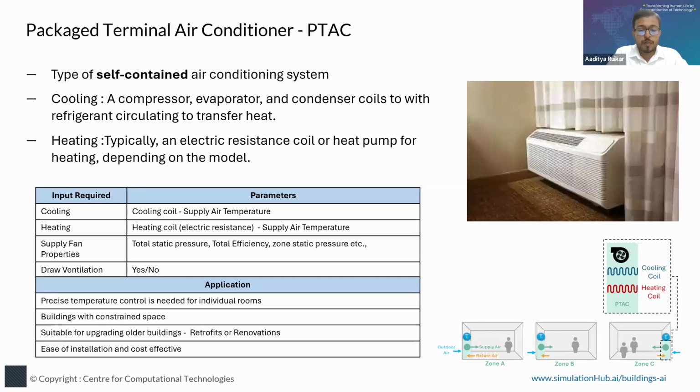So after the water source heat pump, the next terminal system is PTAC, that is packaged terminal air conditioner. As the name suggests, it is a self-contained system with both indoor and outdoor parts. Unlike other systems where indoor and outdoor units are separate, it has both units self-contained in one package.